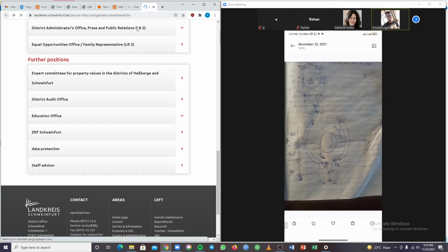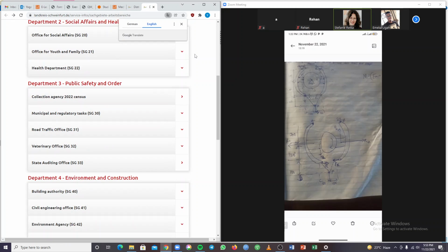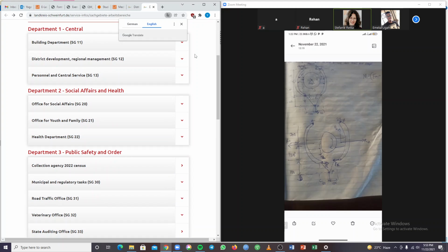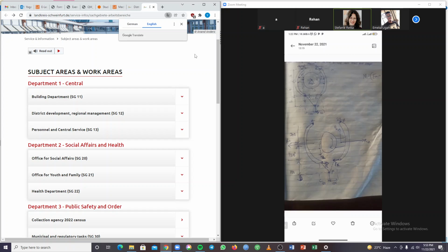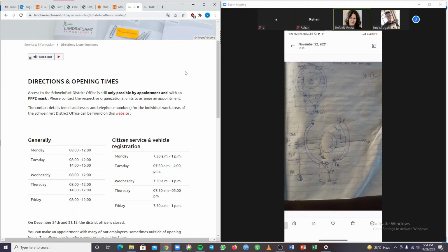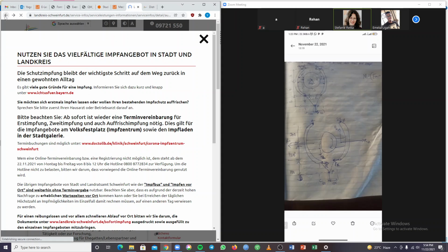Okay. But you have to draw two free body diagrams. One of the entire system by simply freeing from the hinged supports, A and B. So the only additional forces in your system and the free body diagram will be the hinged support reactions in A and B. Everything else stays as in the figure given.